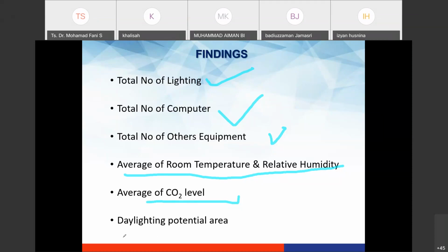because CO2 plays an important role in reflecting the cooling system. When the CO2 level is higher, then something wrong can be detected from the cooling system that we have, for example the chiller or AHU, air handling unit. So we need to do something to get fresh air into the building so that we can balance the level of the oxygen against the level of the CO2.